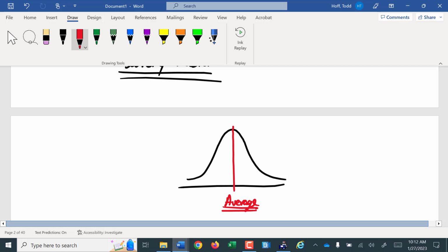Actually, that chart's also on page 157. It shows for a 1/2 inch rope, fiber core, 20,800 pounds of rated strength. But that's average. That would be right in the middle of this curve. Some ropes can hold more than that. Some are going to hold less than that. Well, how much less?